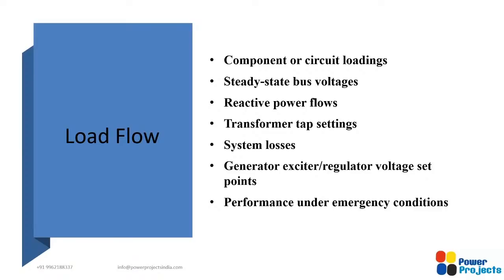If it is operating in a voltage control mode, whether I have to set 100% voltage at its terminal or 101% or 102%, all this has to be answered. This can be optimized using a load flow analysis. So I have not really planned a simulation, but if time permits, we will do that simulation also.